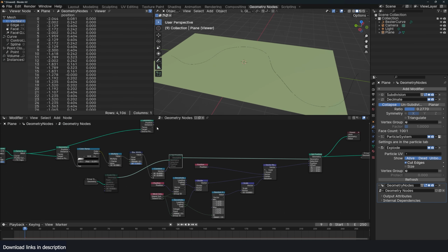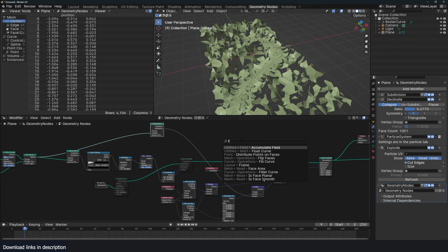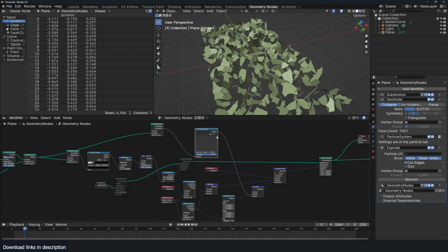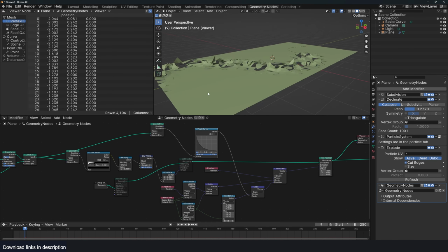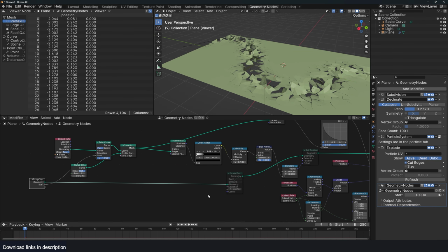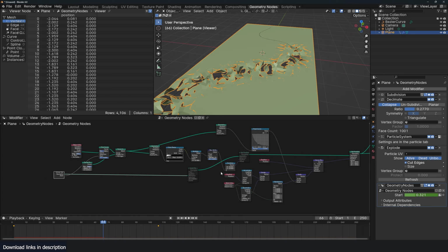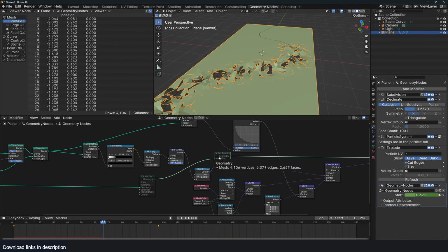So if I use the distance, you can see what we're getting is inverted. So I'm going to use a float curve, flip this around like that. And let's play with the trim here. So where's my group input here? Have this animated. Let's set a keyframe there, and a keyframe at 100. We can have this set to 0. If you set this to 1, it snaps back or creates a bug. So make sure it's just 0.99 instead of 1. And now you can see we have that. And let me also bring back this position.